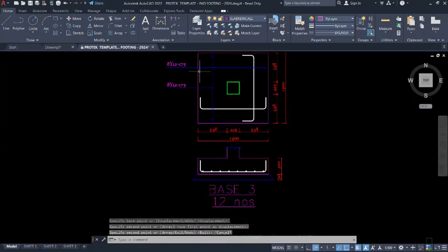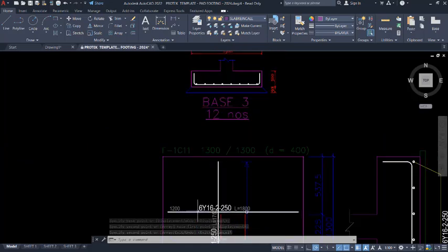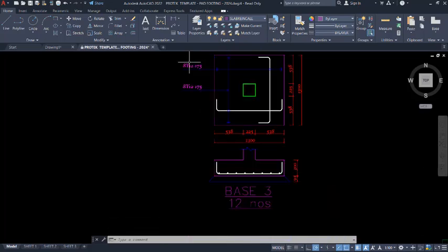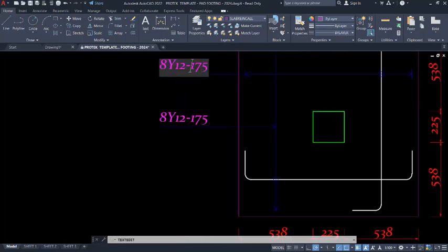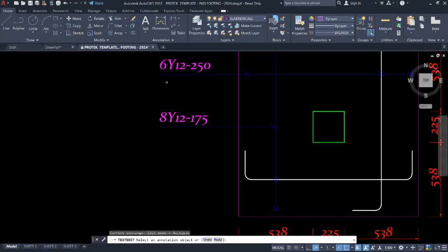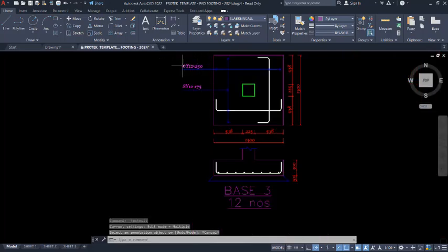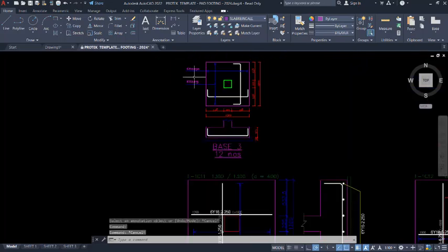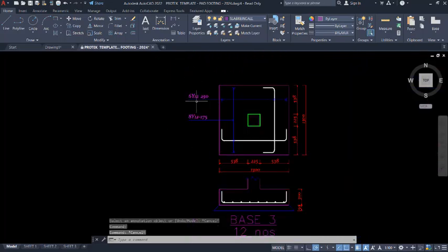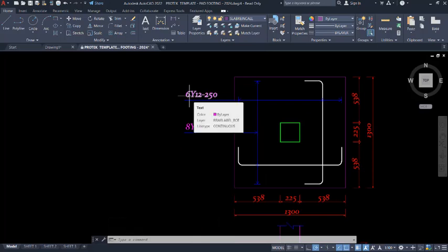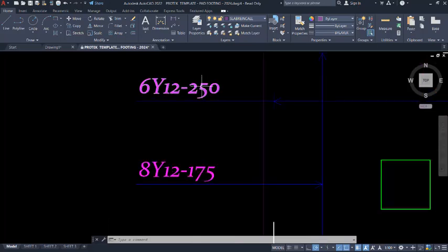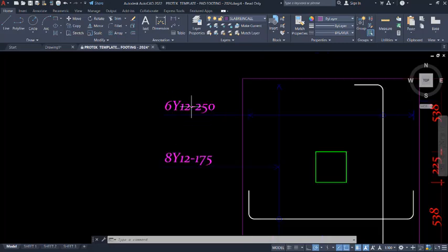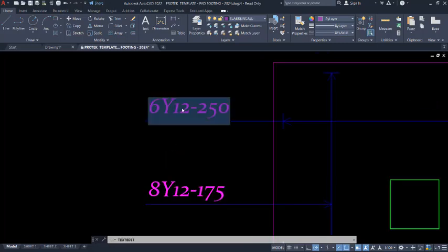Now check the spacing we have here is 250, 6x16 at 250. Over here we're having 8 because the spacing is 175. So you can harmonize that immediately from here. Just key in 250, and then here is 6. You now have to change the rebars to 16. But you can still use it like this because this is 12 and the number of bars increased while the spacing also reduced to 175. But with 166, 6 numbers of bars, you have this to be 16.